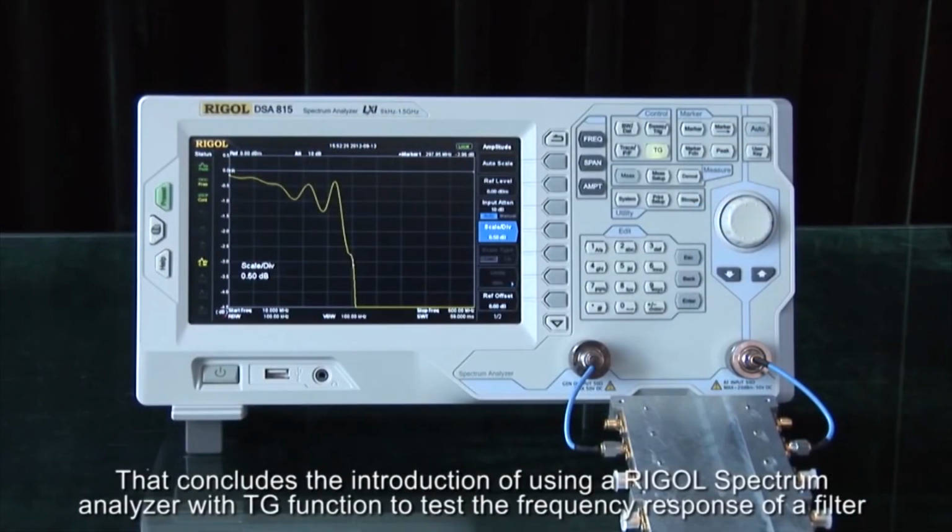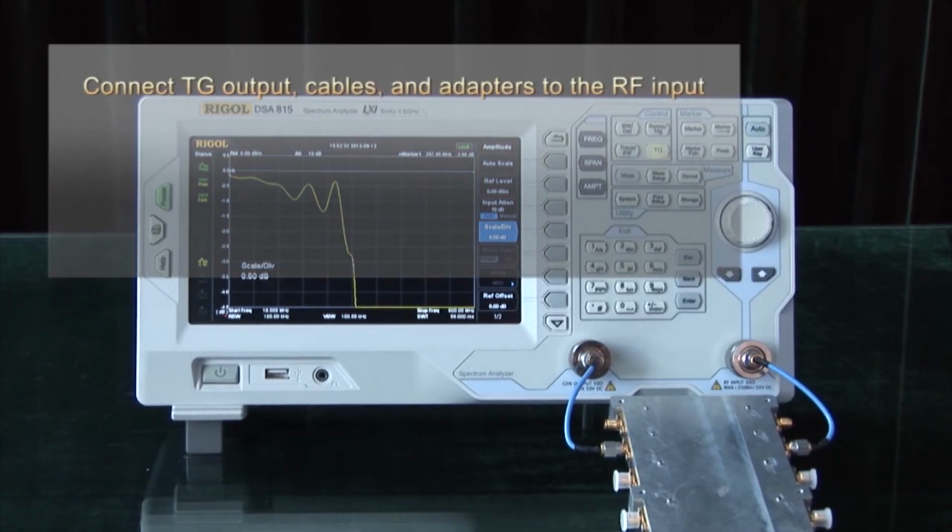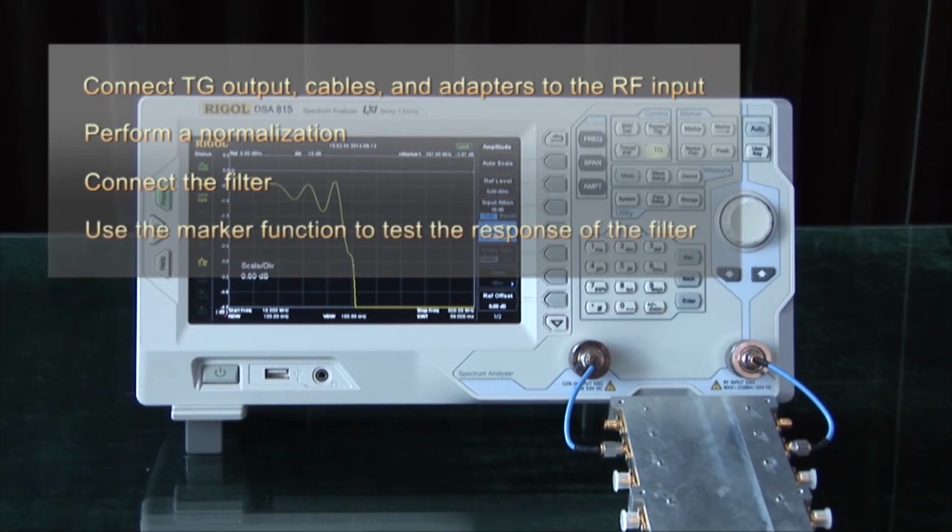That concludes the introduction of using a Rigol spectrum analyzer with tracking generator function to test the frequency response of a filter. Here are some notes. First, connect the tracking generator output, cables, and any adapters to the RF input. Perform a normalization. Connect the filter. Use the marker function to test the response of the filter.